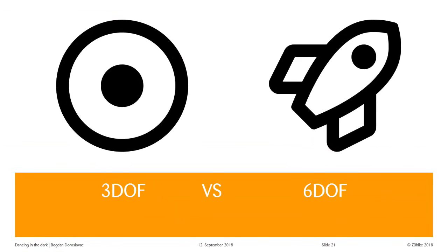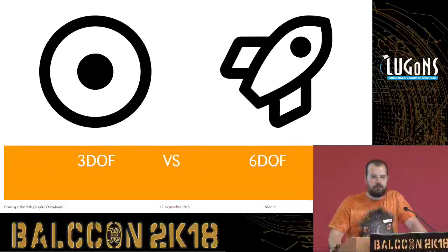Historically, the first ever guided rocket, the V-2, to use accelerometers and to use guidance, actually used a suspended gimbal gyroscope platform for that. It had a hollow area inside it and suspended accelerometers so that they are free, and you can all the time have the platform static relative to the outer shell of the rocket, and basically integrate your merry way through the flight, and hopefully hit London at that time. But now, in modern systems, we don't use such gimbaled contraptions because they are highly complex and highly expensive.